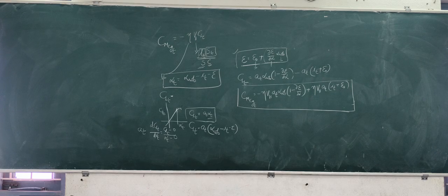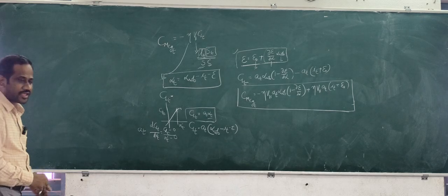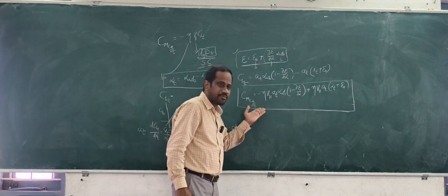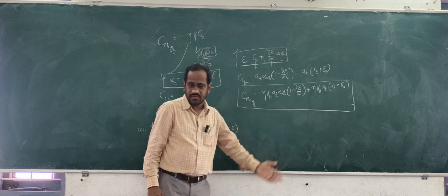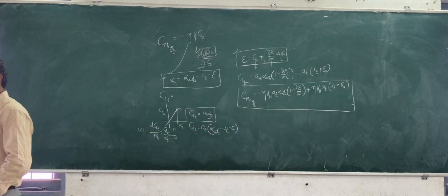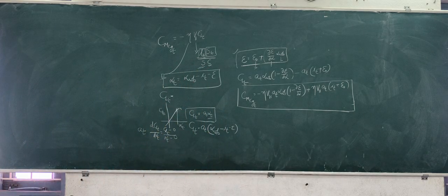It is not the complete total pitching moment. It is only the pitching moment contribution by the tail alone about center of gravity. But what we have taken, epsilon came into picture because of the difference between V prime and V infinity. So the aerodynamic effects of the wing are taken to take the upstream characteristics of the tail. Okay. Now looking at this, we can make some argument.